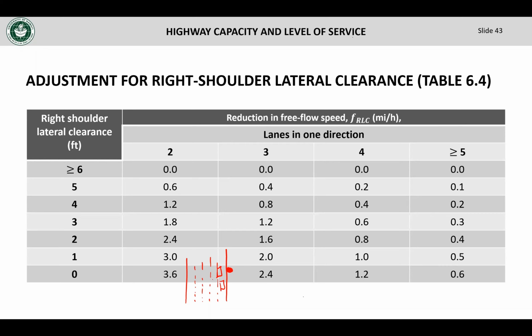And that may affect that vehicle coming on this other lane, which also may shy away a little bit, but then the vehicle in the next lane is going to be affected less. So overall, over several lanes, it is less of a problem than if I have only 2 lanes, right? Because if one vehicle here shies away because of that, then the next vehicle doesn't have much space to shy away to the left. Like you have a lot of room to accommodate sudden movements. That's why it becomes less efficient when we have fewer lanes than when we have more lanes.